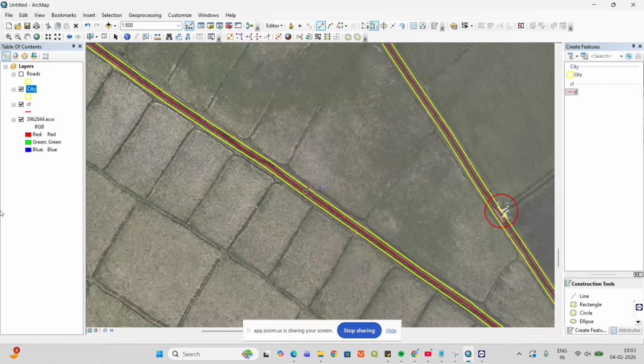But these types of flights are more tricky when you are enabling terrain sensors, because mostly you will enable the terrain sensor only when you're flying at very low altitudes. And the lower you fly, the more possibility of a crash, because you'll have trees, and in some areas you can't predict the tree height.